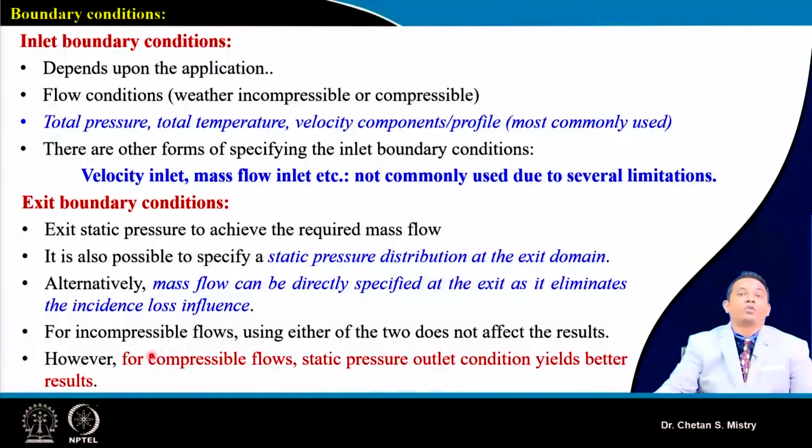Okay, and that too you need to put in an interval, because just understand your computer is not understanding your code. It will get a setup of calculation of different parameters, and that will only be helpful to you in order to capture the shocks. So there is a technique for that, in which at certain intervals, after a few iterations, people are changing the static pressure at the outlet, and that's how they are getting what we are looking for in terms of solution to the problem.